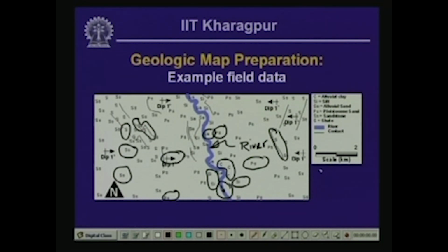Also shown on the map is the approximate scale of the map area. What is not shown here is the topographic contour, and typically large scale contour maps are either obtained from existing archives like the Survey of India, or they are constructed for the specific purpose of a particular project.